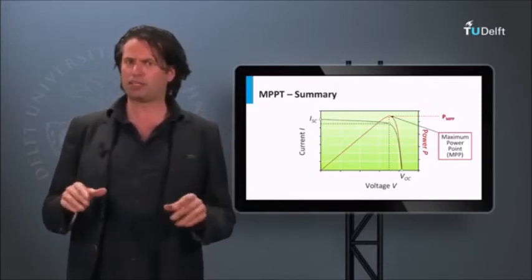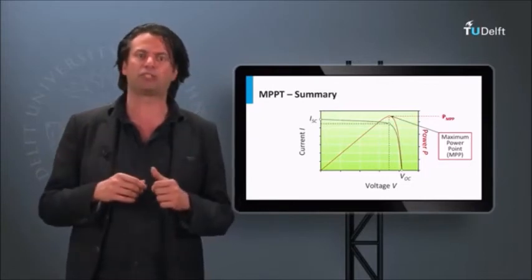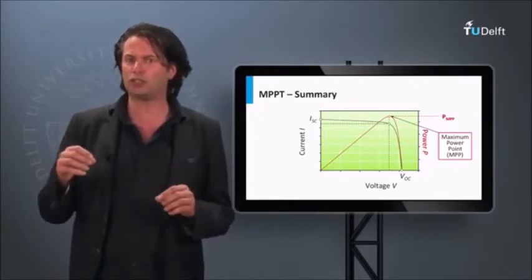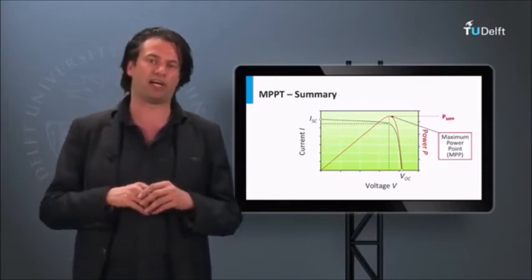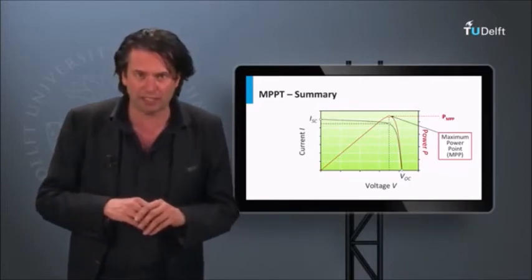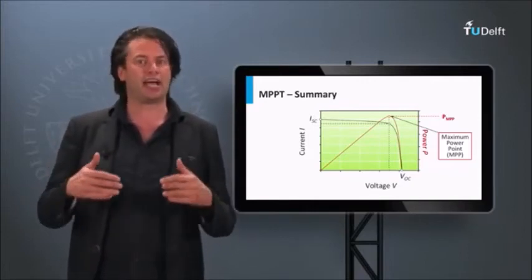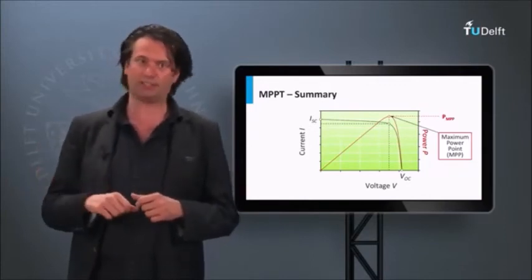In doing so, the device is expected to use as low an energy amount as possible so as to not undo the additional energy gains the maximum power point process provides. The maximum power point tracking device is also expected to respond swiftly and accurately to the changes in the ambient conditions that impact the PV output.